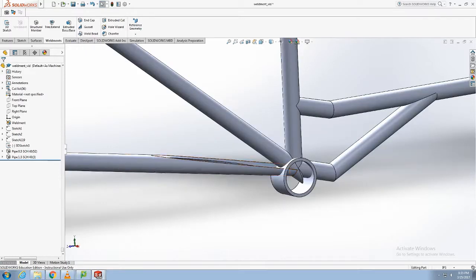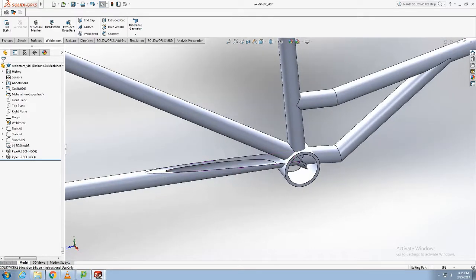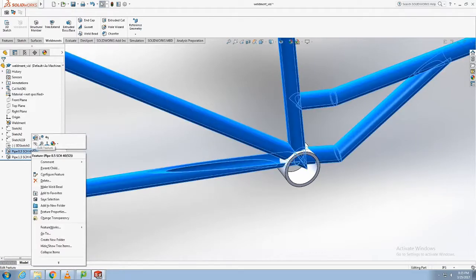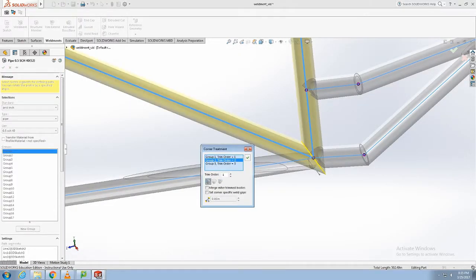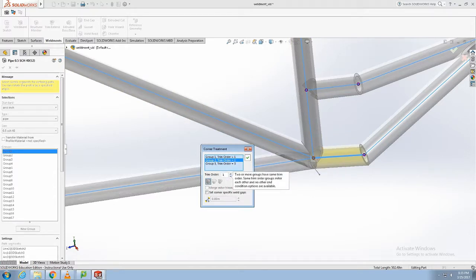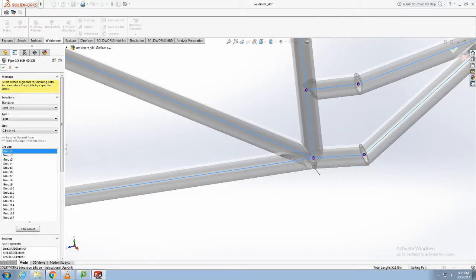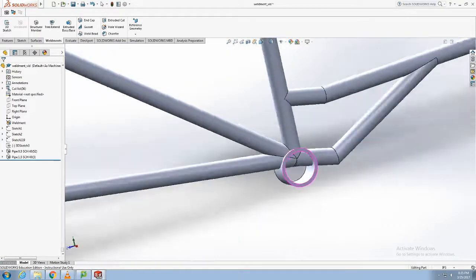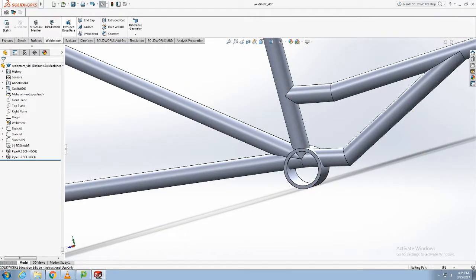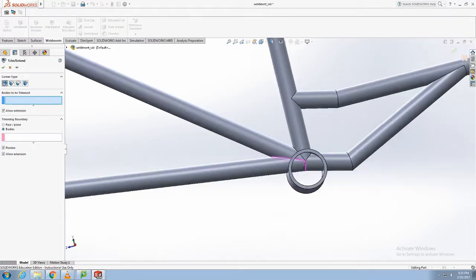Now it is possible to fix all the wonky weldment connections. Right-clicking on the smaller weldment feature in the feature tree and editing it will show purple nodes. These nodes can be clicked on and the weldment connection priorities can be modified by changing the values shown from 1 to 3. Further tidying up can be accomplished using the Trim Extend feature found in the Weldment tab.